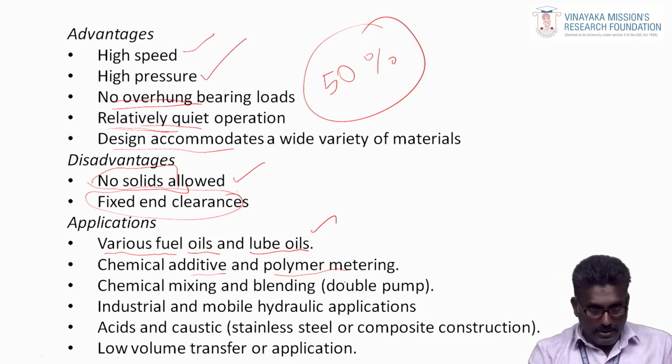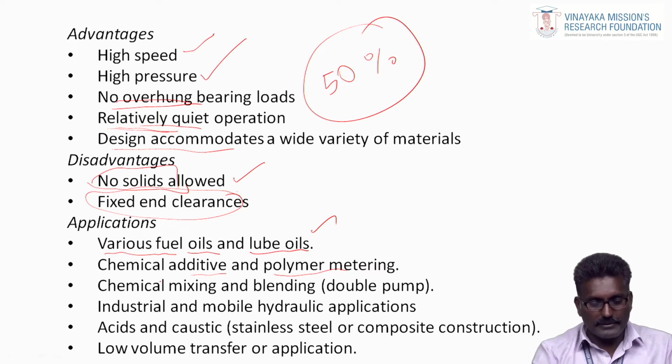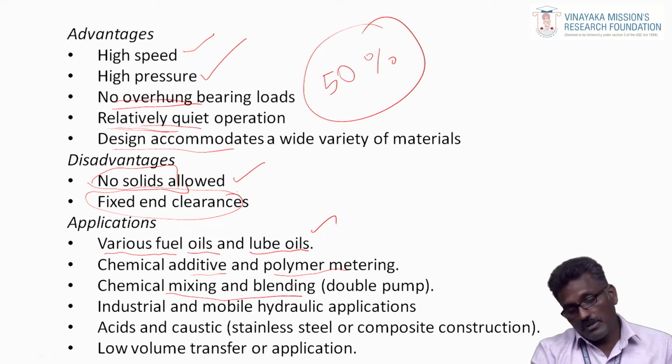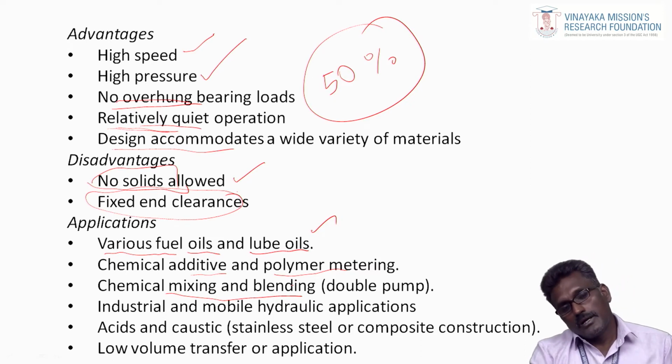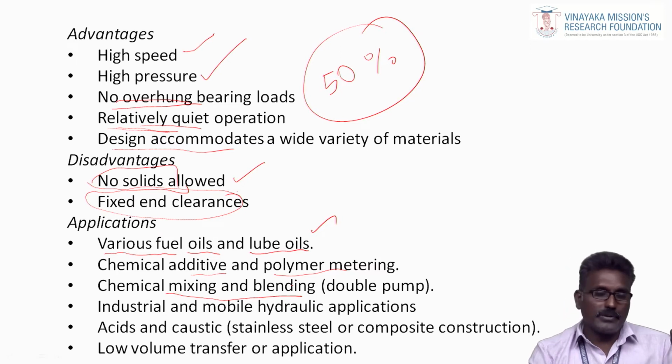We are using a gear pump. We rotate this pump at the required ratio, and we make chemical blending using this pump, because each and every revolution it produces the correct quantity of fluid. That is why, for making a perfect combination, we use this pump with suitable revolutions. Blending is an important application of this pump.